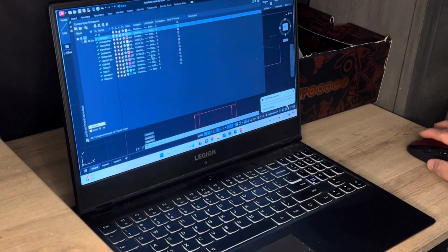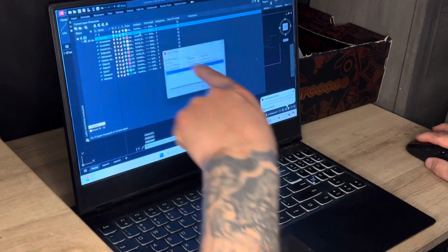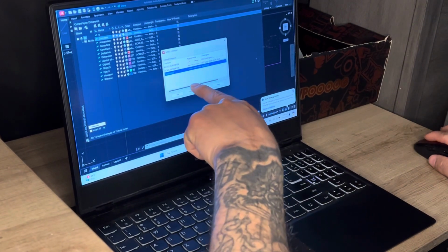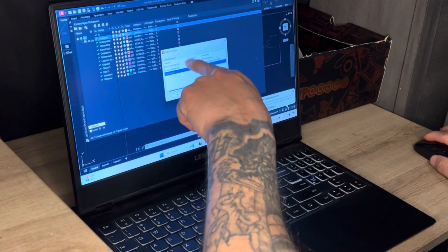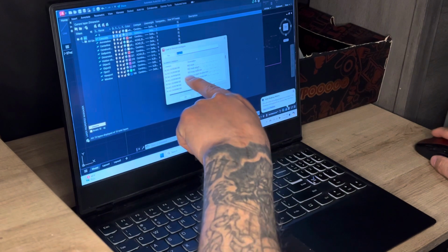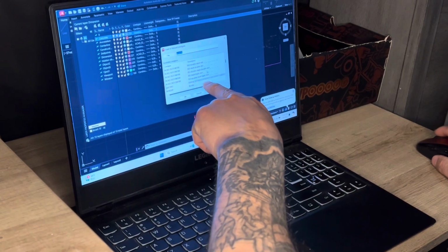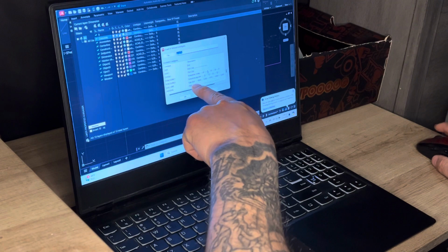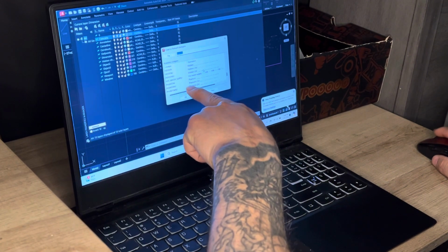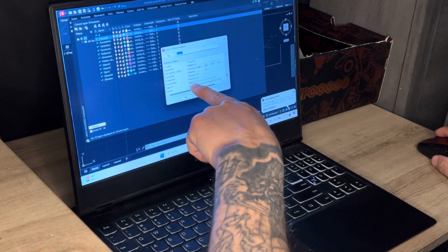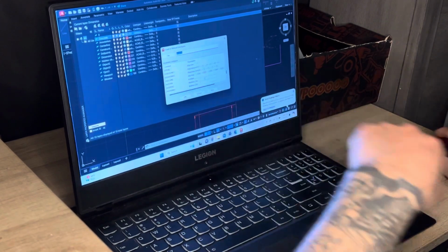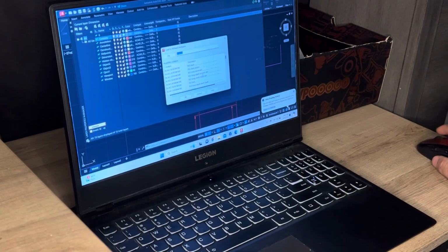Click OK. I could go in here to my line, and I can load lines right here. Right now, these are the lines that I predominantly am using, and so it's giving me those options. But I can load more right here. And it's going to give me all of the standard line types that people use, right? Gas line, fence line, hot water line, phantom line, zigzag. It's going to give me all sorts of stuff in there that I can pick to make this new line.